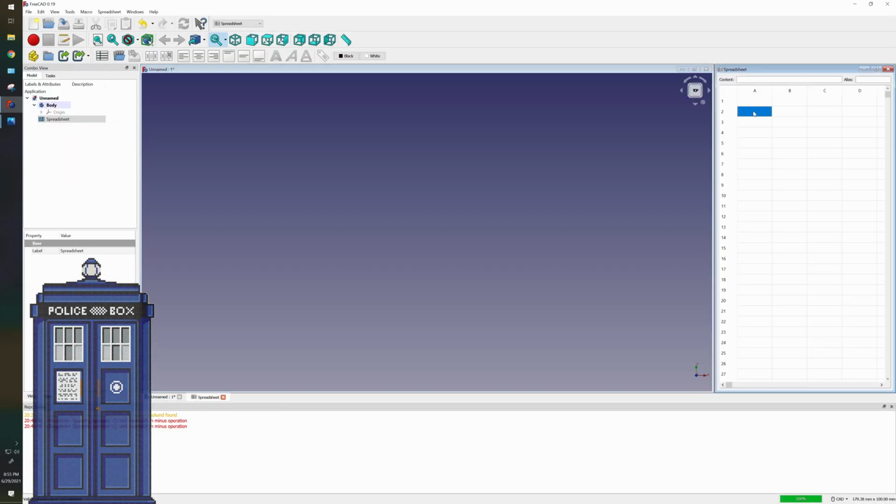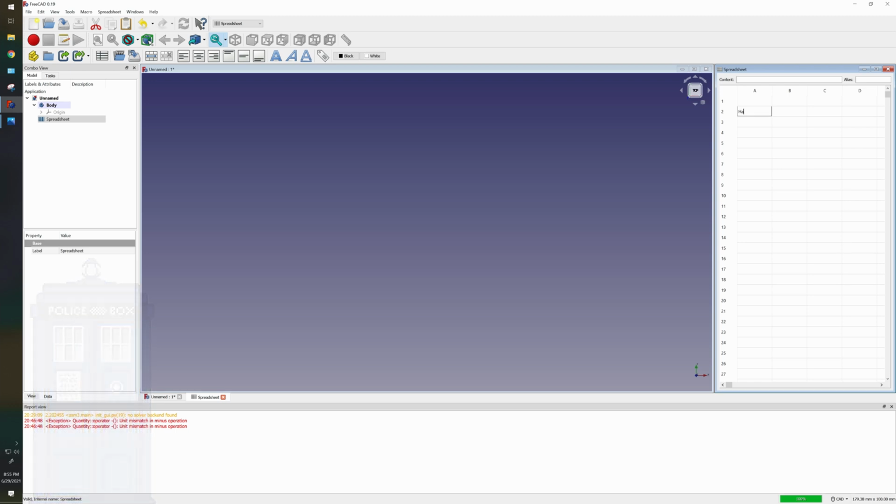So in fact, let's add a couple things here. So let's go hand, outer, diameter. Now you can put spaces in here if you want, but in an alias you can't have a space. So instead of just clicking on every box to find out what its alias is, I like to make my first box basically the alias name. Always gets me because I forget to hit enter.